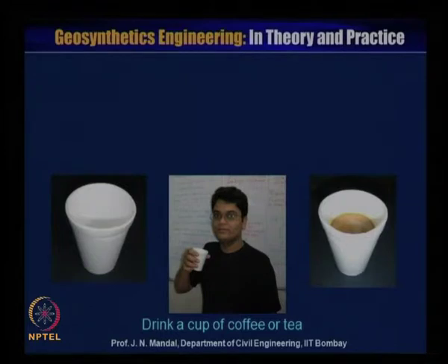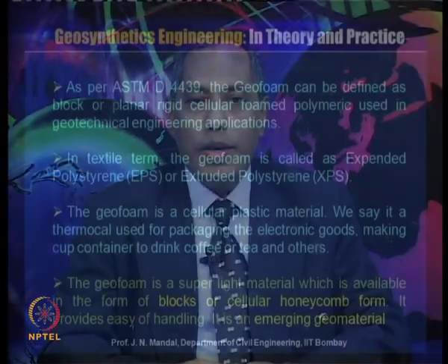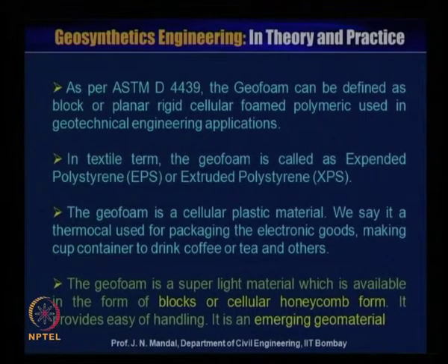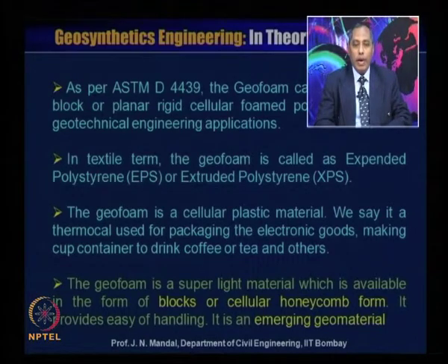So this geofoam has also been included under the family of geosynthetics. As per ASTM D4439, geofoam can be defined as a block or planar rigid cellular foam polymeric material used in geotechnical engineering applications. In textile terms, geofoam is called expanded polystyrene or extruded polystyrene.